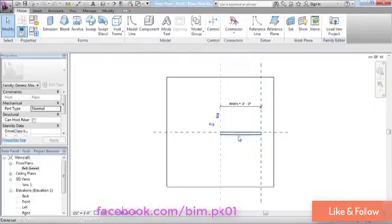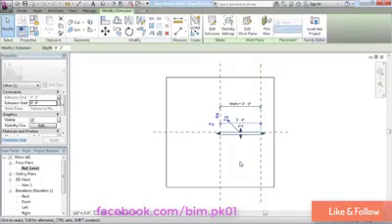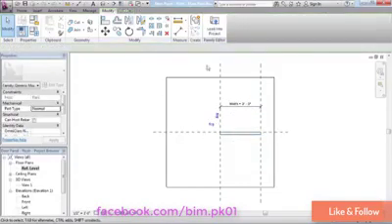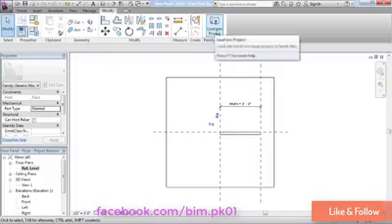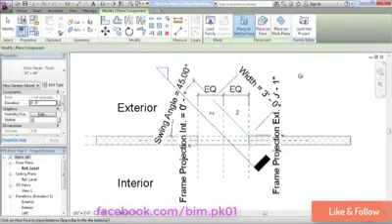Now, otherwise, all that's in here is just a simple extrusion. That extrusion uses the same trick that we did in the previous movie, where the 2-inch thickness parameter is assigned to control the thickness, and then otherwise it's got a width and a height parameter. Otherwise, it's a pretty straightforward family. Let's go ahead and click Load into Project, and that'll take us back to our door family.